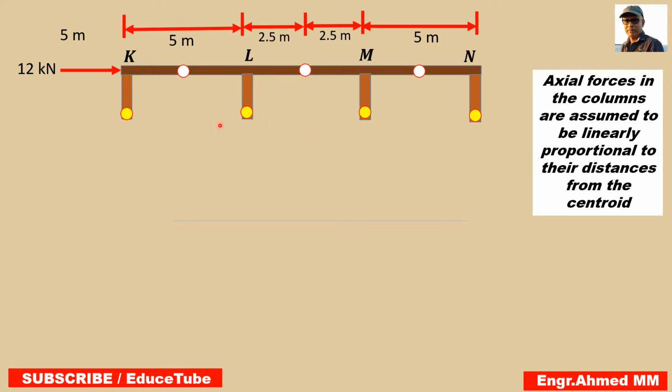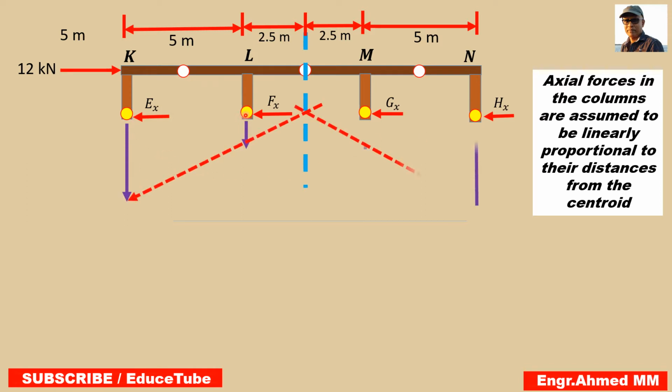So what you can see here are only internal shears and axial forces at the hinges. Shears and axial forces. An important point is there are no internal moments acting on this free body, I mean where it is cut.